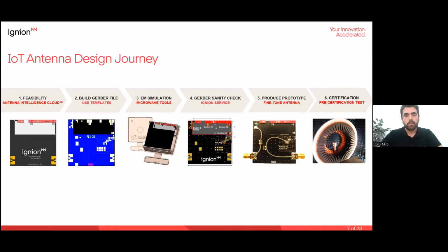desired response. So when your antenna is aligned, in terms of reflection coefficient as well, in the anechoic chamber you verify the antenna efficiency, and then go to the pre-certification stage. Then you will make sure that you fulfill any certification requirements, such as over-the-air tests, TRP, and TIS.